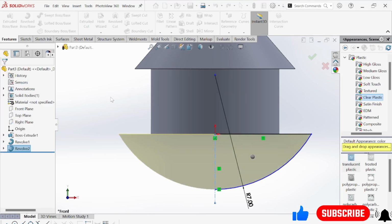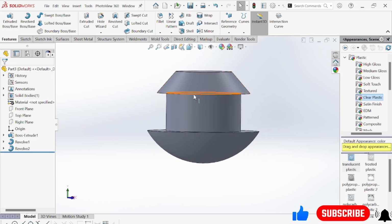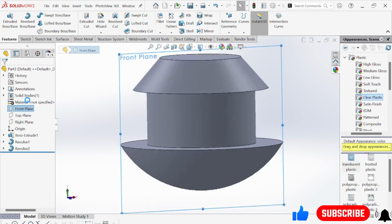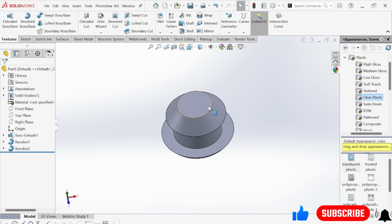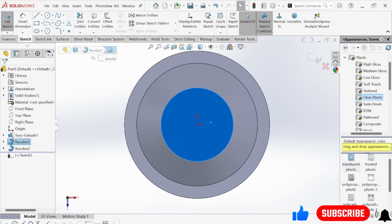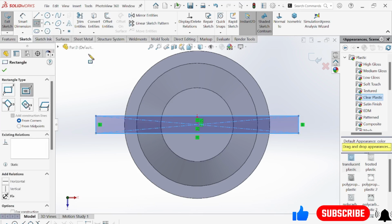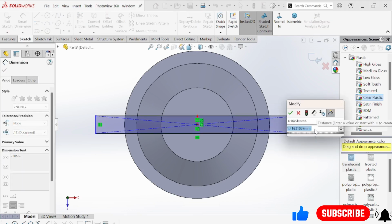Now here you see, this is our part. Now how are we going to use this as a connector? Because we will make a gap here, right? Again select front plane, not front plane, let's select the top plane, because we need to make a cut here. This time select a center rectangle like this. The dimension of this one is not required, just make sure it is bigger than the diameter of this circle. Now here, let's make this one 2.